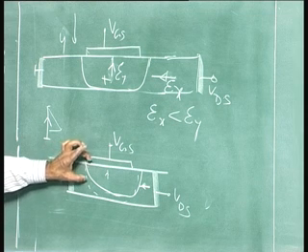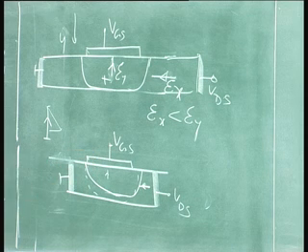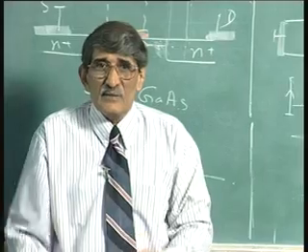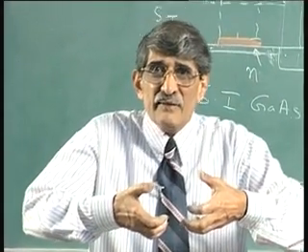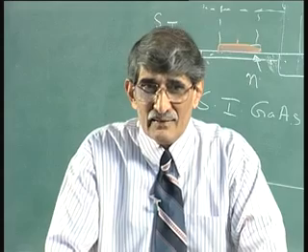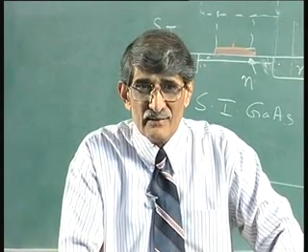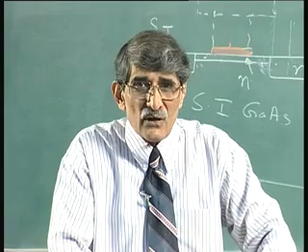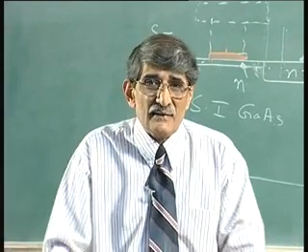So, the result is the depletion layer width, it takes more voltage to close the depletion layer width. You must have higher fields in the vertical direction, so that it is able to close. See, one of the electric fields is pushing it down like this, the other one is pushing it in a different direction in the 2 dimensions. So, as a result, you require a larger field in this direction to close the channel.